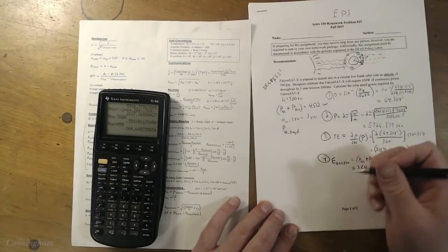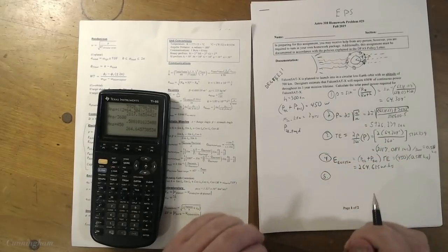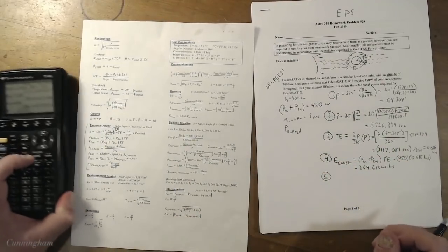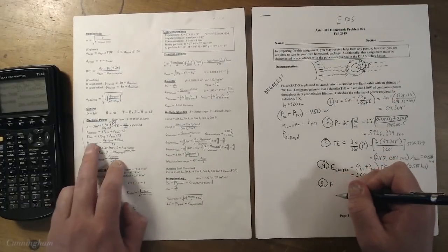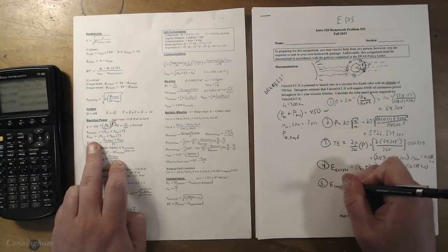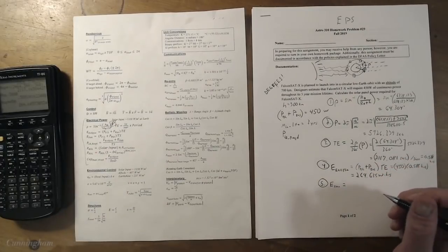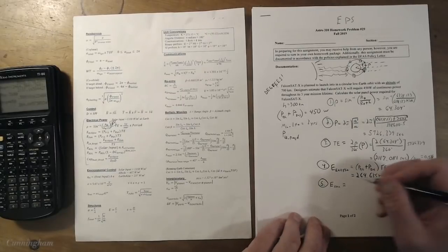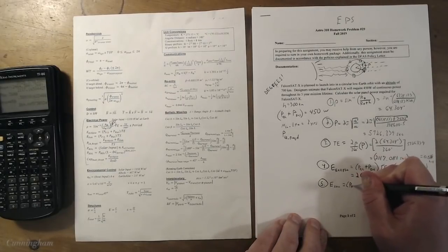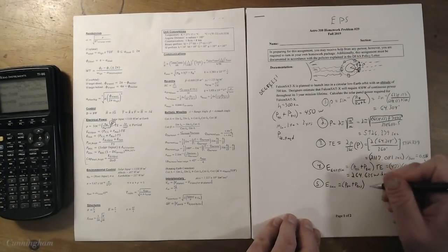Okay, now let's find the amount of energy we need in the sun to both run the payload and the bus and recharge the battery from when it was being used in eclipse. That's the next thing we need to find. We're just marching down the equation sheet here. Energy in the sun, energy needed to power the battery and the bus and the payload in the sun. So we're going to take that power sub payload, power sub bus, and multiply that by time in the sun.